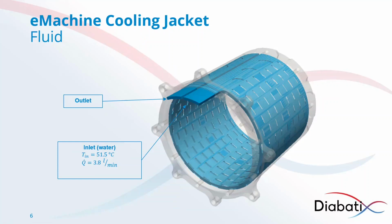Then in the fluid region, which is shown here in blue, we have an inlet at which we specify the temperature at which the water enters the domain, and the flow rate, which is set to 3.8 liters per minute. On the other side, we have the outlet.